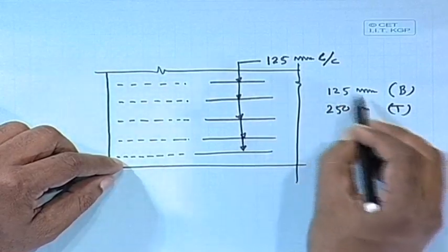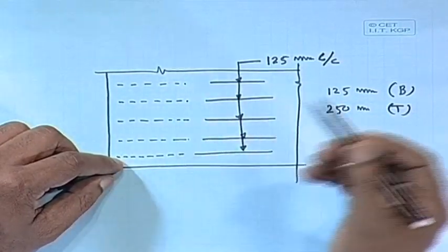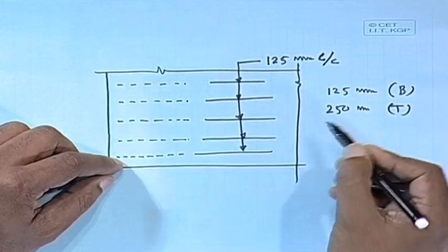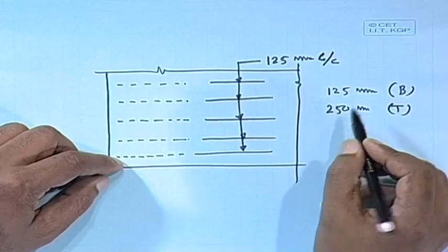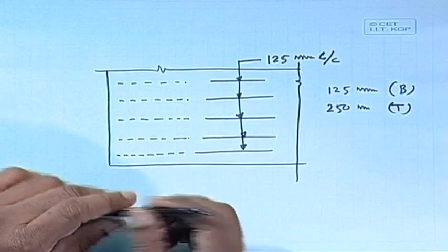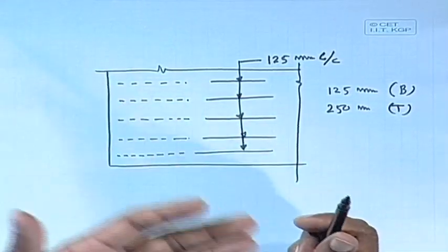But if it is say 130, 140, the alternate one may not be 240 or 280, that we cannot provide, it has to be restricted to say 250 maybe. So, your top and bottom bars, all of them are dependent. Here in this case, when you are making that separate one, the detailing for the top as well as for the bottom, there is no dependency, and so we can go separately for top bars as well as for the bottom bars, and that is what we nowadays follow.